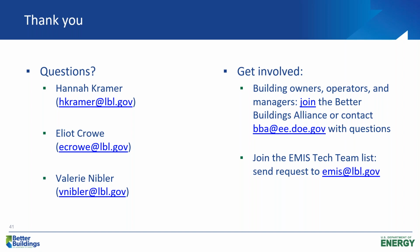There's some other ways to do FDD, like with IoT sensors. So you're kind of building up a simple BAS with sensors, but it's hard to do a full FDD installation the way that these tools are generally set up, with hundreds of different rules looking at all sorts of things, without a comprehensive set of data. Your faults are only going to be as good as the set of data that you have to base them on.